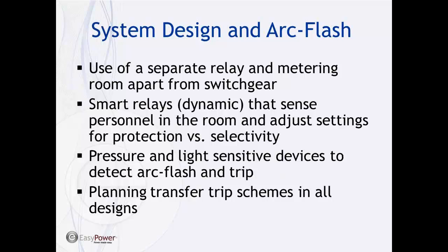Smart relays, so that if you walk into a room, you automatically enable those maintenance mode settings or a second group of settings that reduce the hazard around the equipment that people are in proximity of.